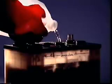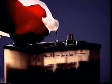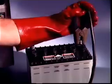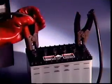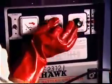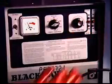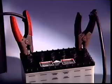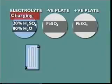The cells are sealed from each other and filled with dilute sulfuric acid. The battery case is usually plastic or hard rubber. One set of plates is connected to the negative side of a DC source, and the other to the positive side. Direct current is applied to the plates, changing them chemically until the battery is ready for service. In a discharged lead-acid cell, the active material of both plates is lead sulfate.